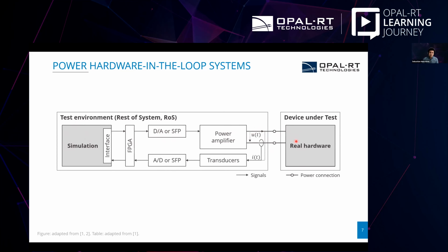The device under test will react in some way, and here, exemplarily, the current is measured and fed back to the simulation environment, again via the signal chain. In order now to enable electrical interactions, step sizes of the simulation environment are required to be rather low. This is where the challenges arise, as we are talking of hundreds of nanoseconds up to 50 microseconds, which would be a typical value for the simulation of power grids, for example.